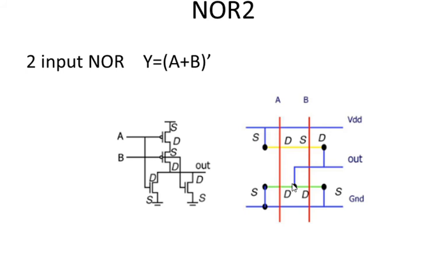To avoid the length of layers, we are using the notations like this. If we use the drains on the other side, the length of the metal layer will be increased. Always we have to minimize the layer length. Accordingly we need to place the terminals of the transistors or any other devices.